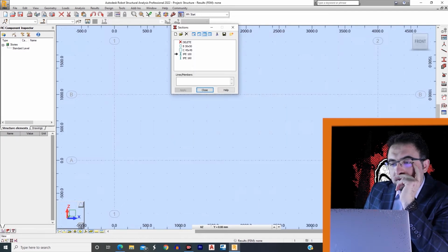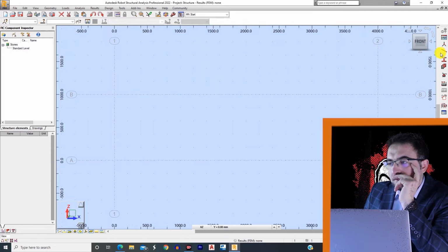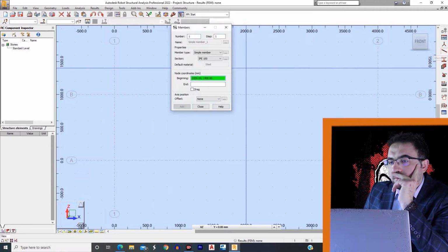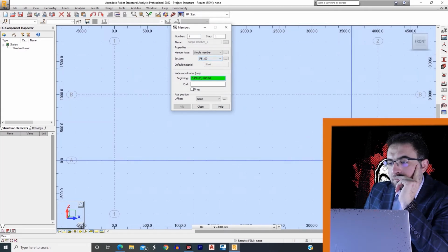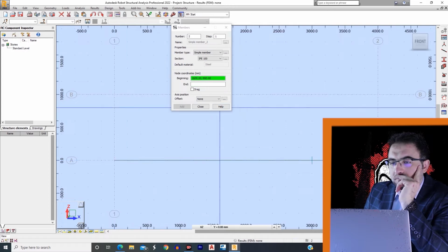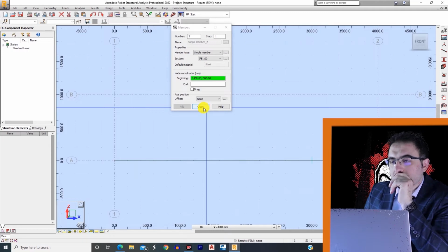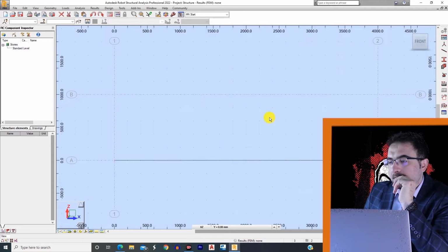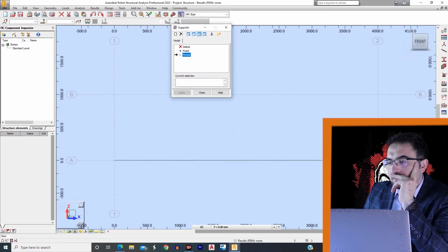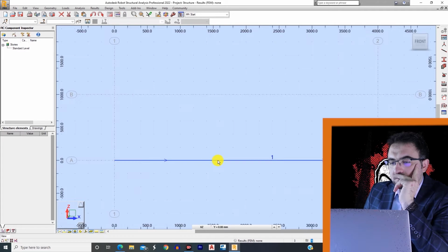I can do the same things, but I will not. So I choose this. It's okay. Then define the bar. For example, I just click here and click here. Okay, it's good. The number is good. So close. Then for support I choose pinned, here and here. Okay, that's good.